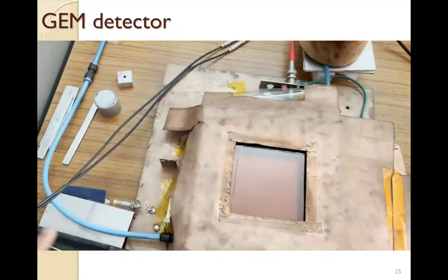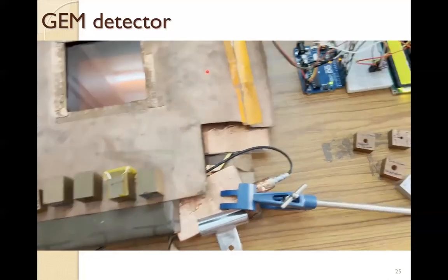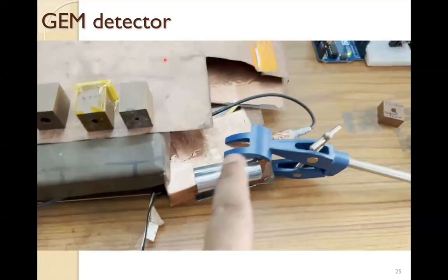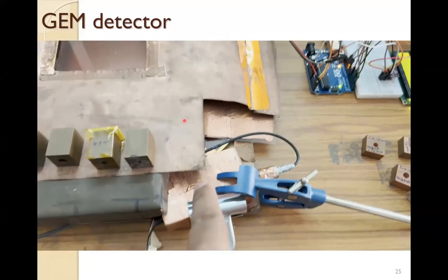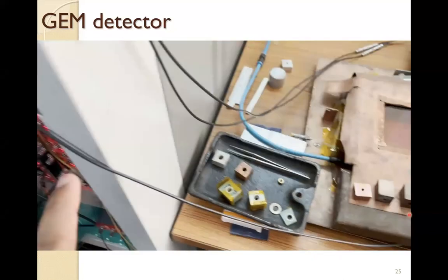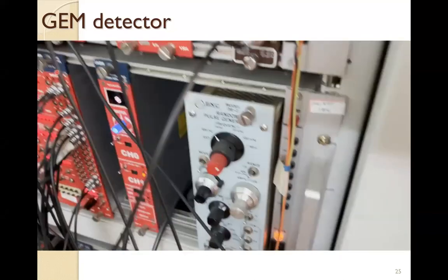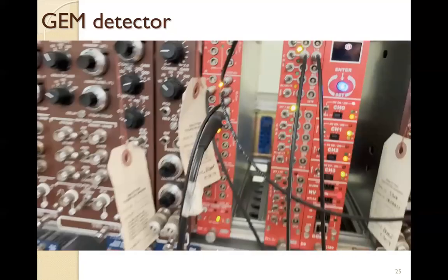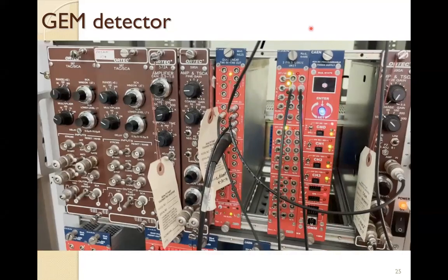So this is the high voltage connector. The dividers are here. We have used this copper plate for shielding purposes, electromagnetic shielding. So this is the preamplifier. The preamplifier input is here, and it is going to the electronics. After the preamplifier, it is going to linear FIFO in. You can see from this we have taken 4 signals. One is fed to SCA, where Shayok used this SCA as a discriminator, and one we have put to MCA for the spectrum.